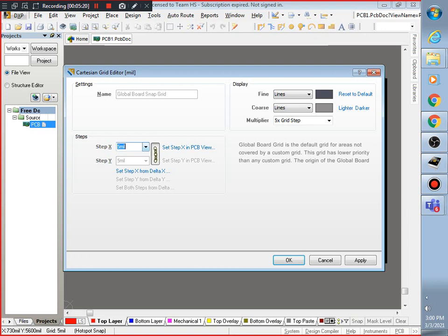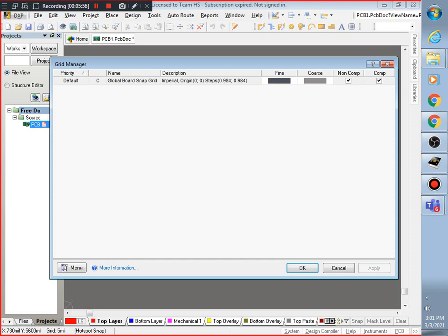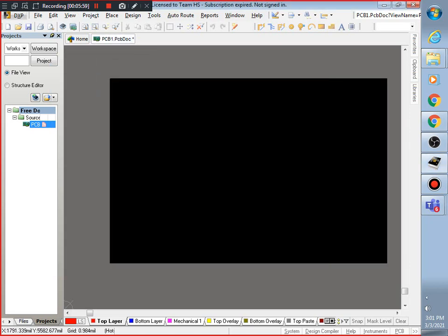This one is telling you how minutely you can move anything in the X direction or the Y direction. So here I want to use the minimum, so I am selecting 0.025 mm. Why this one? Because when I am going to align some 7 segments or some transistors or some resistances, I want to keep my PCB very small in size. So I am just going to drag them very close to each other without violating some rules over there. So this is going to be 0.025. I will click apply, OK, click again apply, OK.